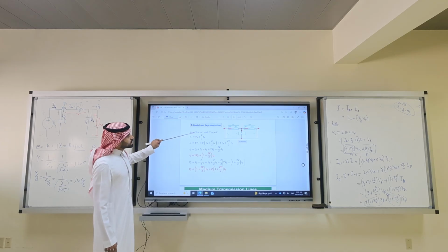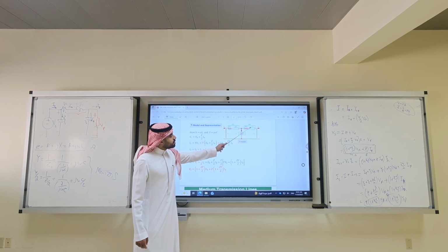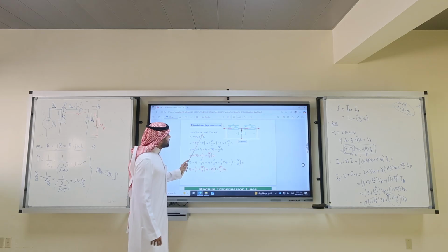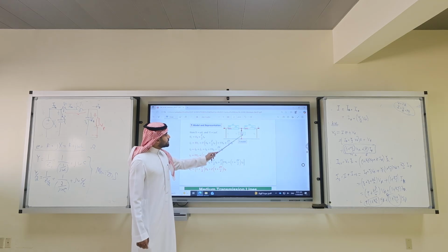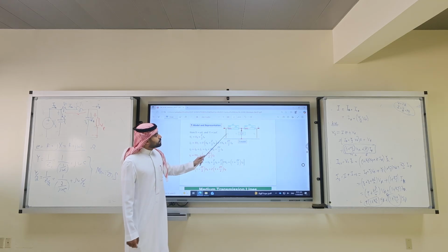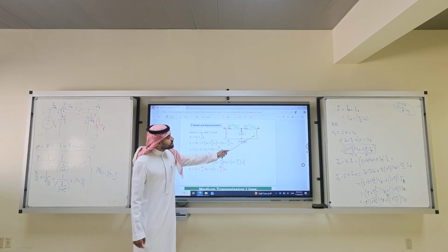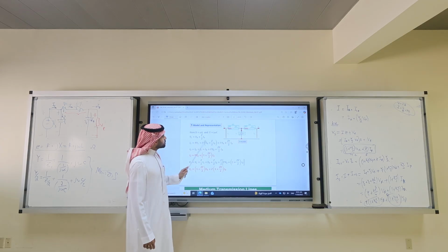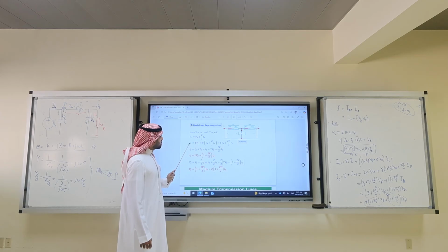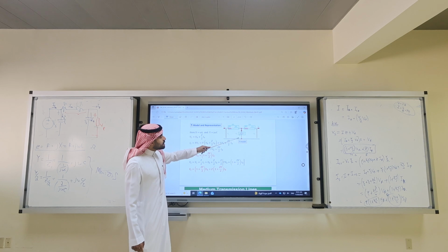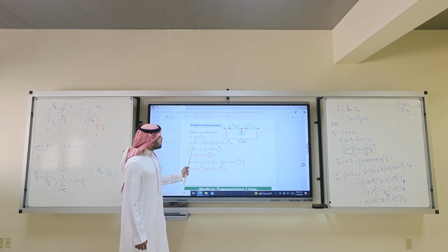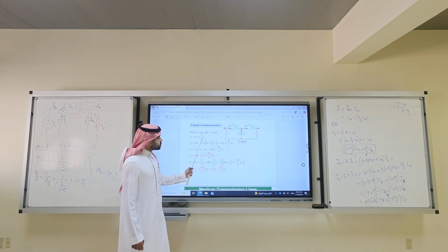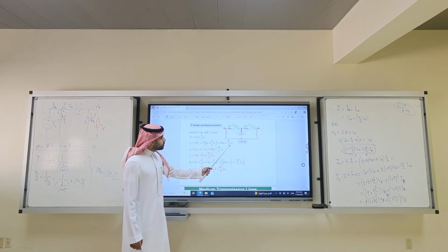So what is X? This is X, which here is X over 2, and X over 2 is omega L. What is Y? J omega C. What is VC? VC is VR plus IR Z over 2. What is IC? IC is VC times Y. This is the VC, VR plus Z over 2 IR, times Y. So this equals Y VR plus ZY over 2 IR.